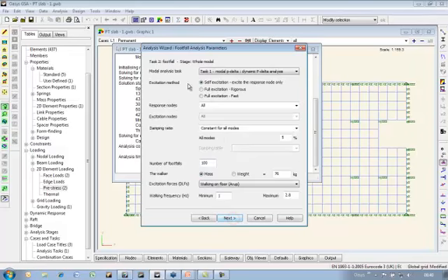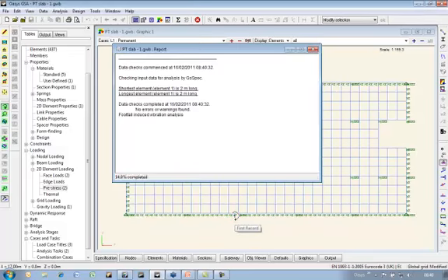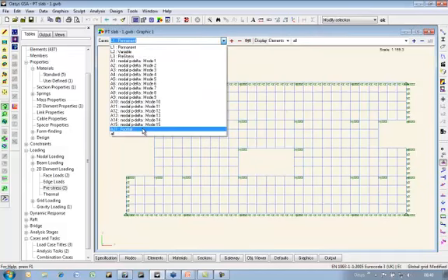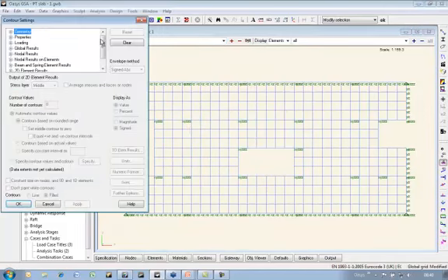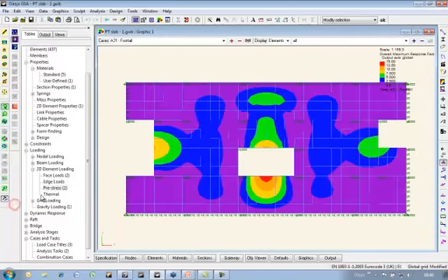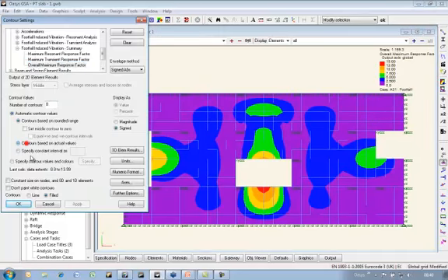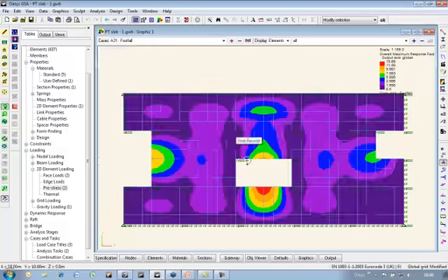So, with our analysis done there, let's do a new analysis of the footfall. Again, fast, take 2%, analyse that. Now remember, the flat slab was coming in just under 5, response value 5. The response value here is much higher. Actual values: response value of 14 in that location.